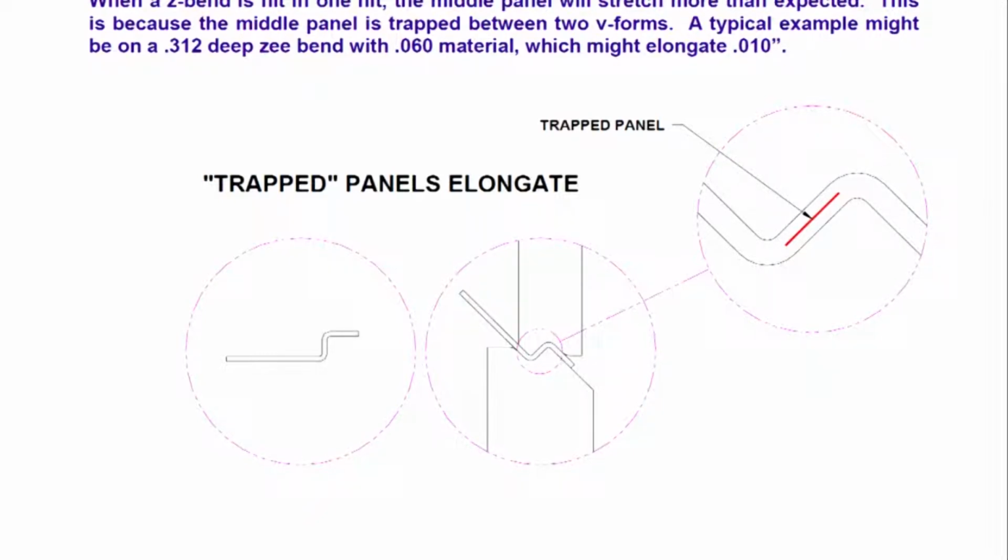Inside, the spot weld items like this here, and if you see the proportions of it, typically the total step we get is about 4 to 5 times the thickness of the material. So, without occupying too much space, we can make the sheet stiffer by putting these Z purlins inside the sheet. Fabricate it, once again we end up with these things, and then